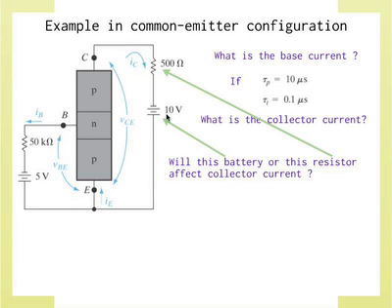There's a small difference. This is my reverse saturation current, which means that the voltage that I apply on this side, in reality, will have some small effect on the collector current. So the impedance is not really infinite. That's the answer. It has a small dependence. In an ideal diode, yes, it's pretty good.